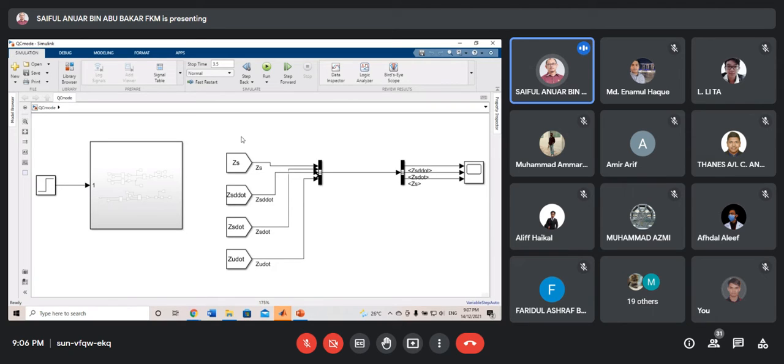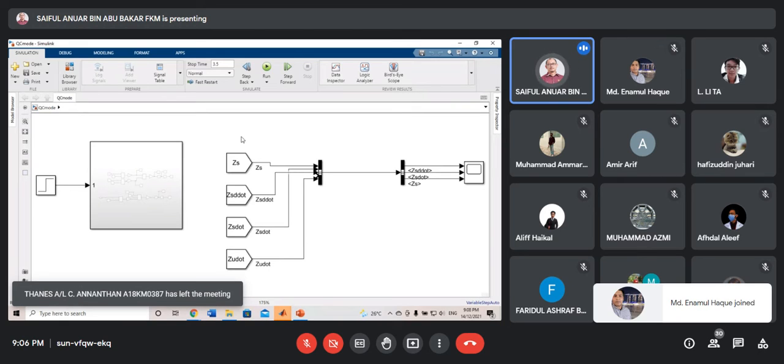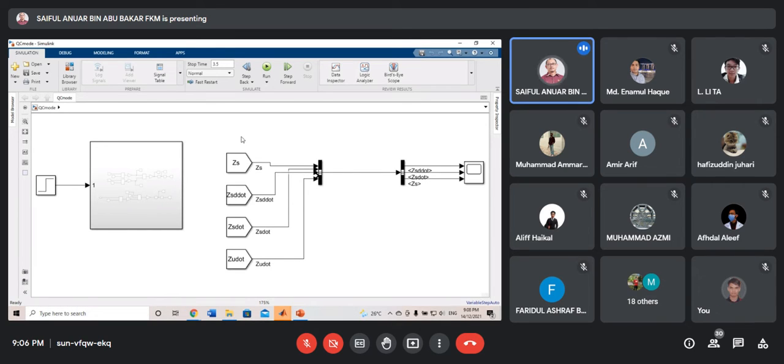Sebab Raspberry Pi we have the input channel is just digital. Most of the sensors that we have, for our easiness, usually we prefer analog or anything that has support inside Simulink for Arduino. So we use that for Arduino. So the Arduino being integrated or assembled with the sensors just to do the data collection. That data then later on will be passed to the Raspberry Pi through the serial connection.